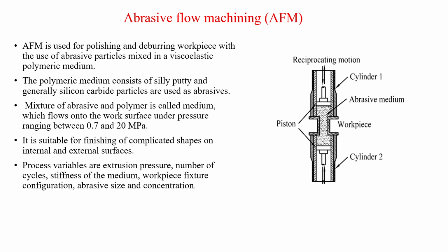The polymeric medium consists of silly putty and generally silicon carbide particles, which are used as abrasives. Very important point: the mixture of this abrasive and polymer is called the medium, and it flows into the work under a pressure of 0.7 to 20 megapascal. It is suitable for finishing very complicated shapes.